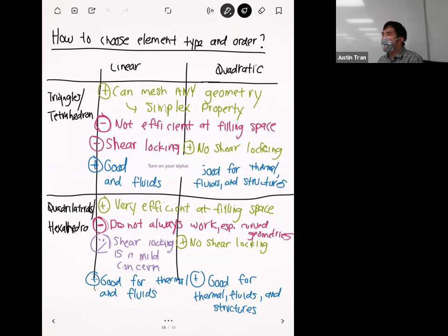Roughly you can think of it as, for each level of refinement, level 1, level 2, level 3, the element sizes are going to be that many times smaller compared to the global size. So refinement level 3 means it's going to be about 3 times smaller than the global size. For example, if our global size is 2 millimeters, then it will be 3 times smaller. Exactly. So it'd be two-thirds of a millimeter. Thank you so much. No problem. Have a good weekend.